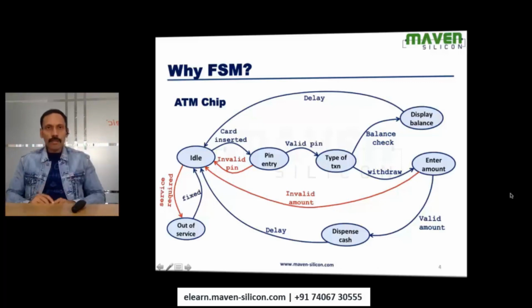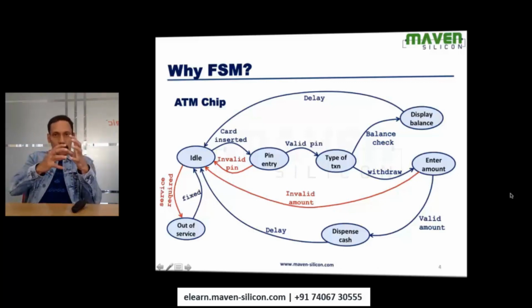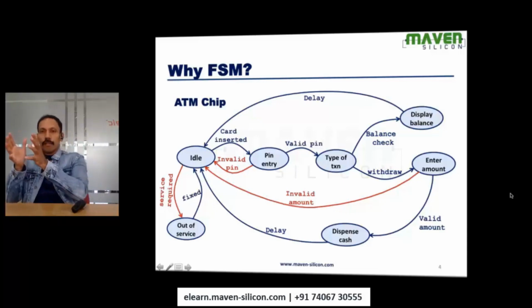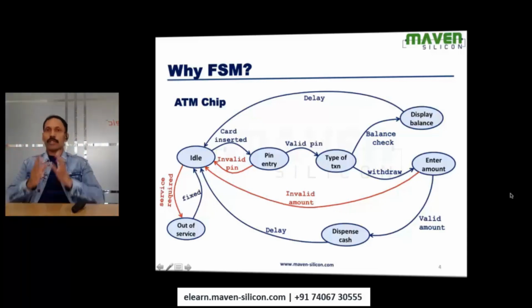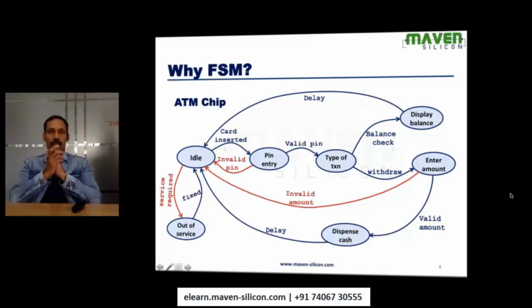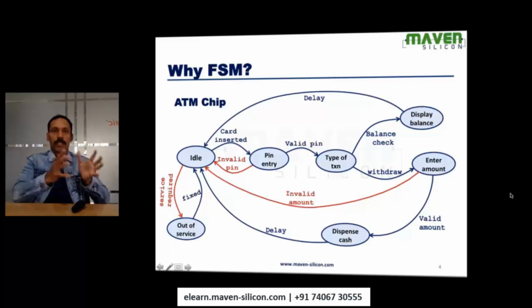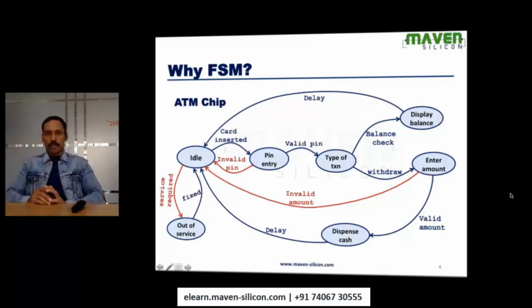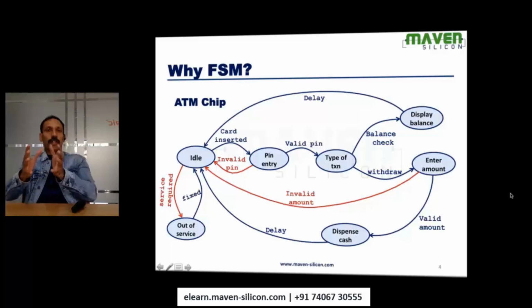Okay, that's fine. After designing this FSM, what do we actually do? We extract the logic circuit from this FSM. So we identify the flip-flop, what kind of flip-flop we want to use, T or D or JK flip-flop. Then based on the excitation table of that particular flip-flop, we define the logic function and then we try to minimize the terms. And based on the minimization, we create an optimized logic circuit. This is what you are going to explore during the advanced digital course.